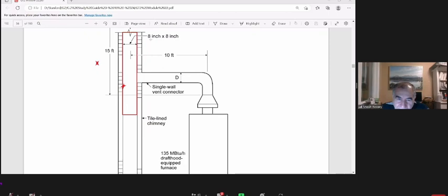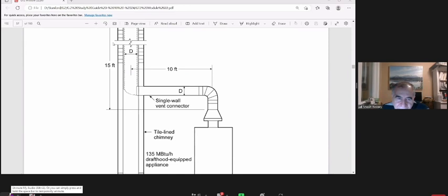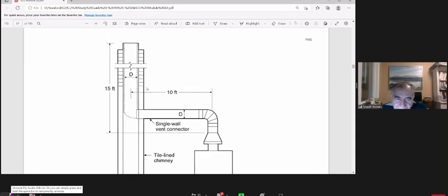Those are some conditions that I will let you know later on. Right now, just see what a chimney is, single appliance. Here they put a chimney liner. If you remember, when we use a chimney liner, you have to reduce 20% and go on table C1, C2.